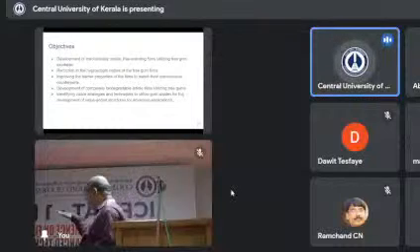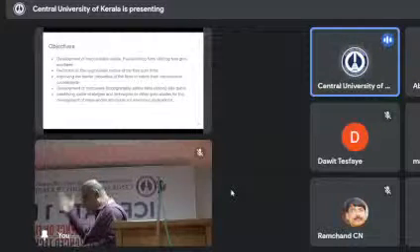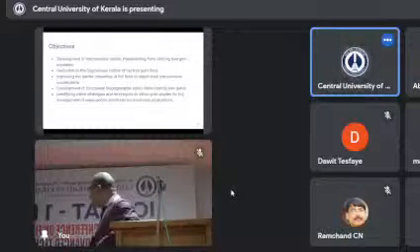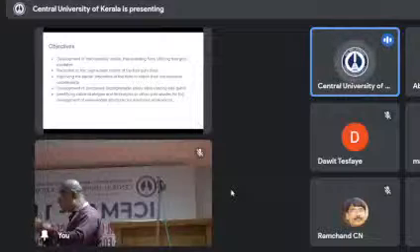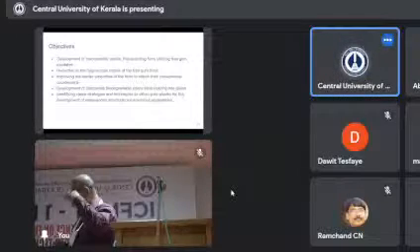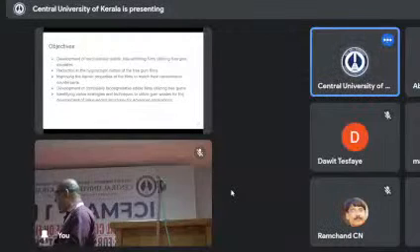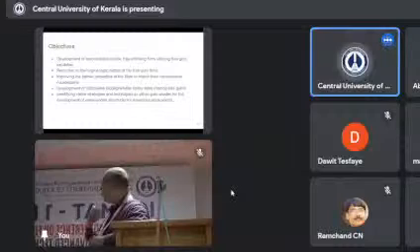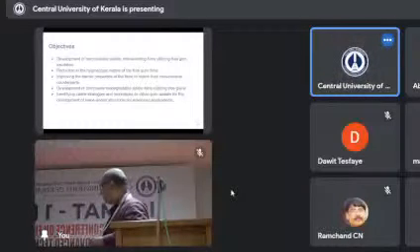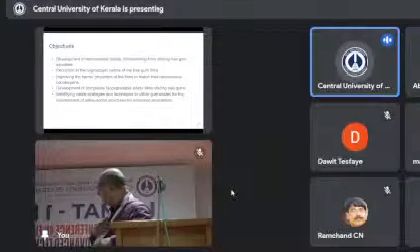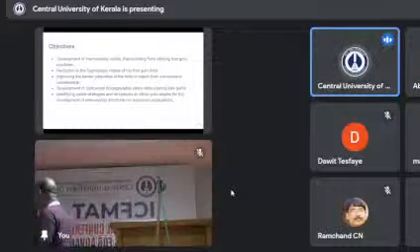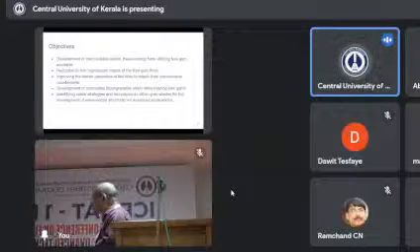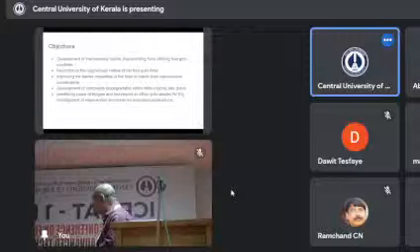So these are the main objectives: how we can use functionalization to improve mechanically stable freestanding films from these three gums, and how we reduce the hygroscopic property of these gums, making them hydrophobic rather than hydrophilic, and improve the barrier property in the film by functionalization of the gums, and the development of completely biodegradable or edible film by using these gums. And later we can use them for some advanced application of these tree-based gums.